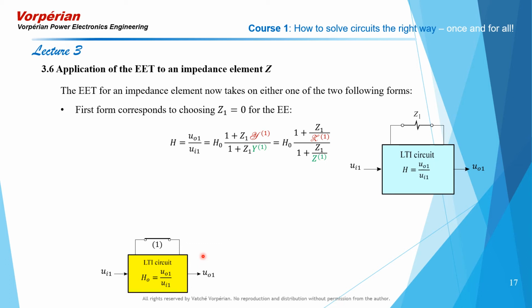Next, we had to perform two additional calculations, which were the inverse gain with respect to Z1, once with the response nulled and once with the excitation set equal to 0. The response null calculation was for the numerator, and with the excitation set equal to 0 was for the denominator. So in the next block, what we did was calculate the input admittance looking into port 1, the ordinary driving point impedance looking into port 1, with the excitation, of course, set equal to 0.